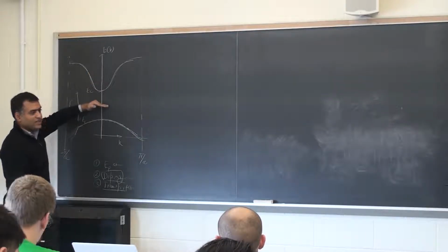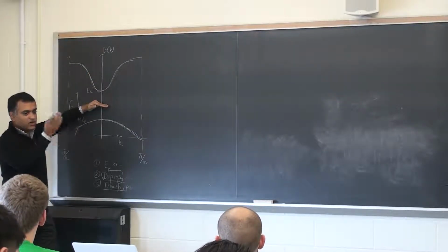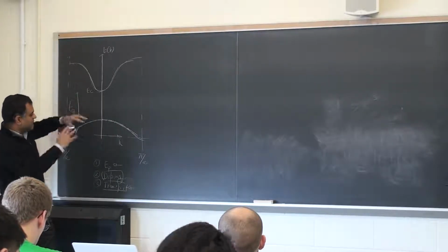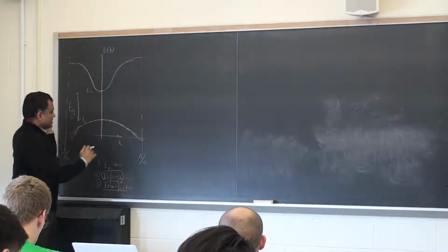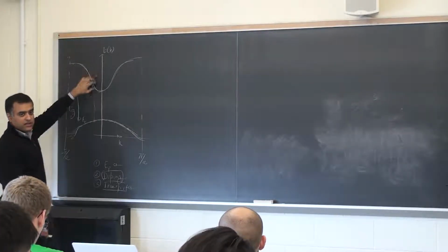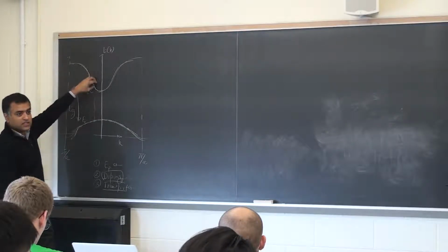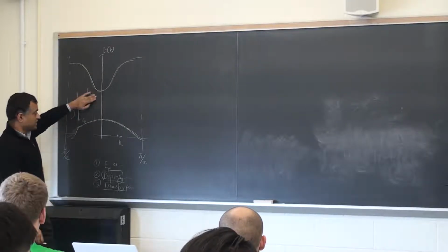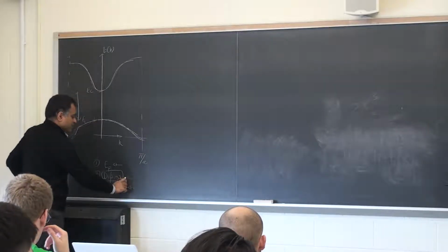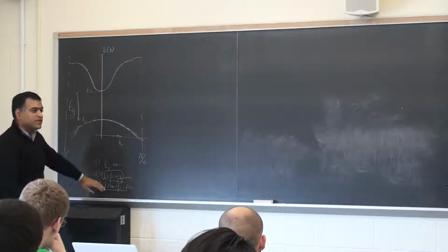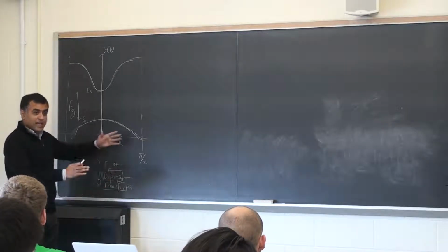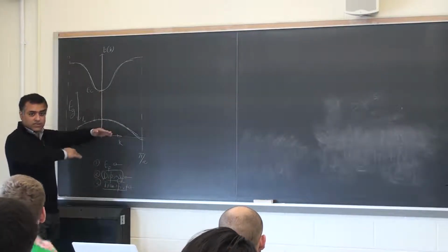where you apply a gate voltage and you move the Fermi level into the band, and it looks like a metal, move it back, it looks like an insulator, and you have on, off, and high conductivity, low conductivity, and so on. So the third method is you can shine light on it, photons. The photons can come in and kick up electrons from here to there, empty out these states, fill these states. So that's the heart of photonics as well. So there are three methods, but we'll look at the passive method, which is doping, which is you just change the elements, the chemical composition. And then later on, we'll look at the active methods, which is gating or photons.